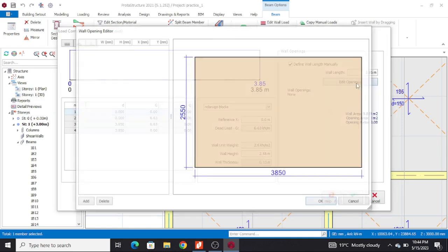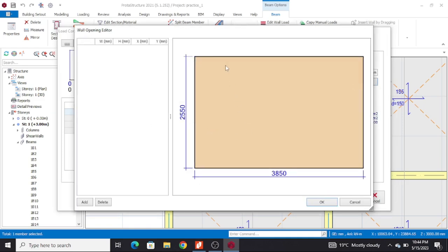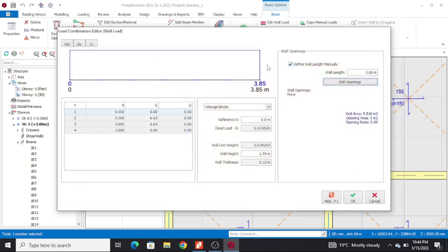Also, you can edit openings. I'll show you in another video how you can do a door or a window in a wall, but to be safe, just do full walls. You never know, sometimes the client or the developer might change a door, or the architect might change the position of a door or a window, and you had designed for a window to be at a certain place, and that is going to affect your design. So in most cases it is preferred you do 4 walls.